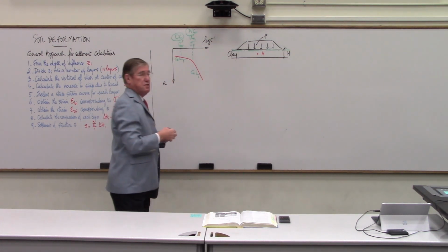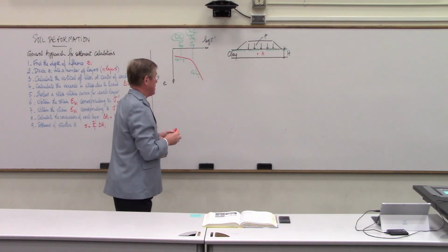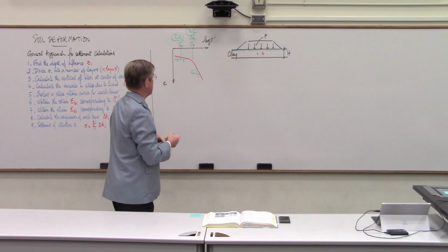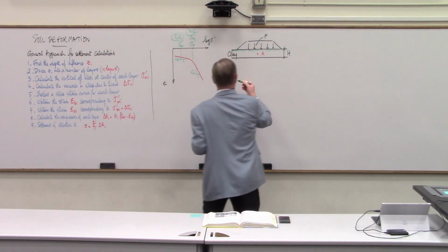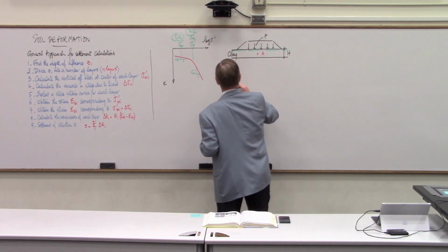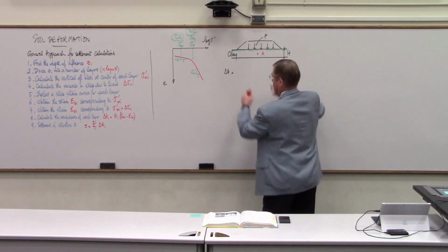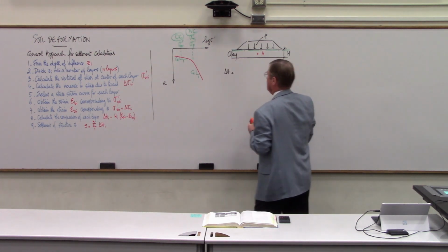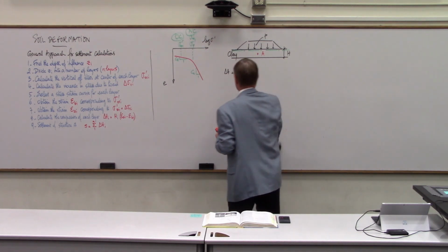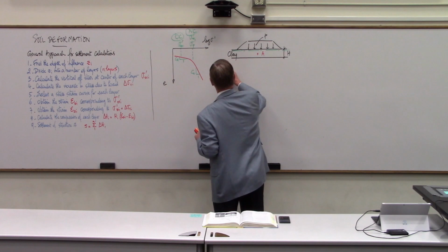We're trying to calculate the settlement of this structure, of this embankment. So we need to write down that the settlement, we'll call it delta H, is equal to delta H, C sub C, and so on. There's an equation that does that, but there are several cases. I'm going to deal first with the simplest case, where the material is normally consolidated, okay?